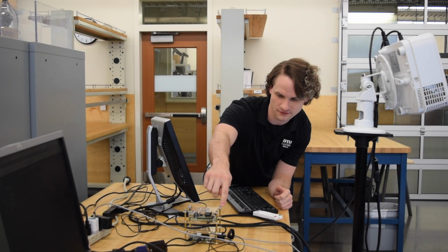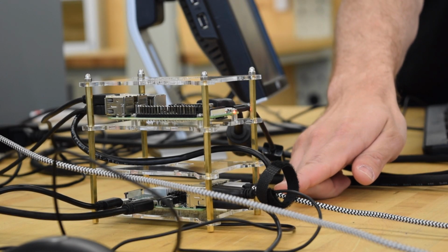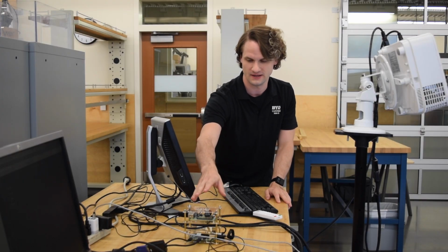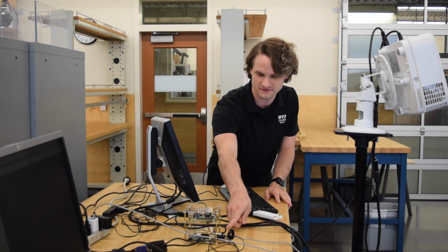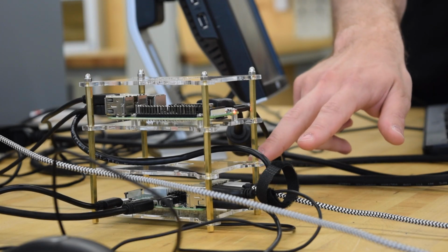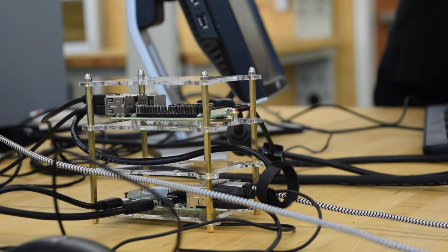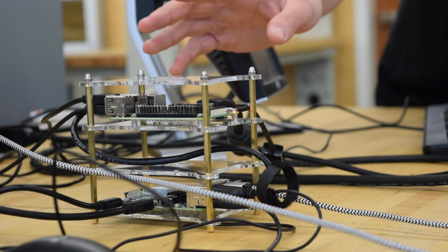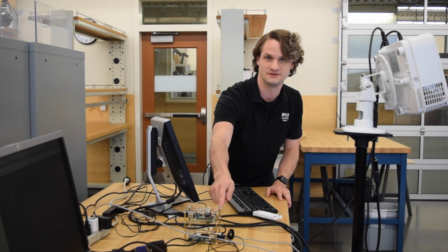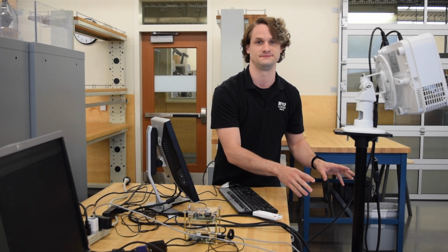So we have 2 Raspberry Pis, and the first Raspberry Pi is connected to the software-defined radio and does all the calculations for the angle. It stores those angles in an HTML file, and then the second Raspberry Pi generates all of the visualization you see based on those angles that are stored. And so there's an Ethernet connection, and a C++ script runs on that second Raspberry Pi to read in all of those angle values into the visualization code.